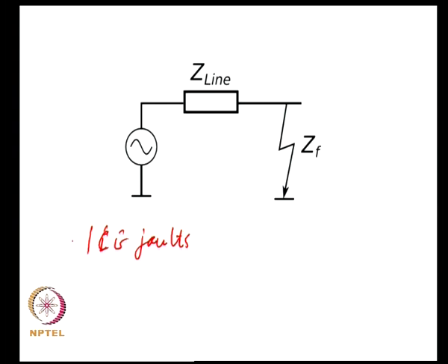If you look at solid 3-phase faults, they are much more rare. Typically around 5% of faults might be 3-phase faults, but the main benefit of 3-phase faults in your calculations is that they are simple, and it is something you could readily calculate.